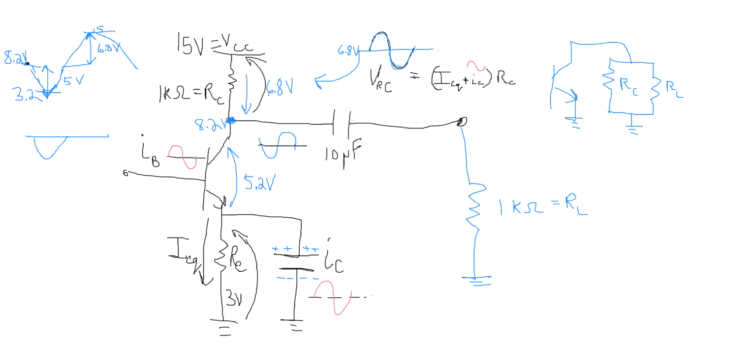So there's a contradiction here, an inconsistency. Here's what's going on. The transistor's voltage does rise, but it only rises halfway, about 3.4 volts. Because at that point, the collector's current would be diverted to the load. So rising 3.4 volts shuts off the current in the transistor and diverts the rest of the current through the load.